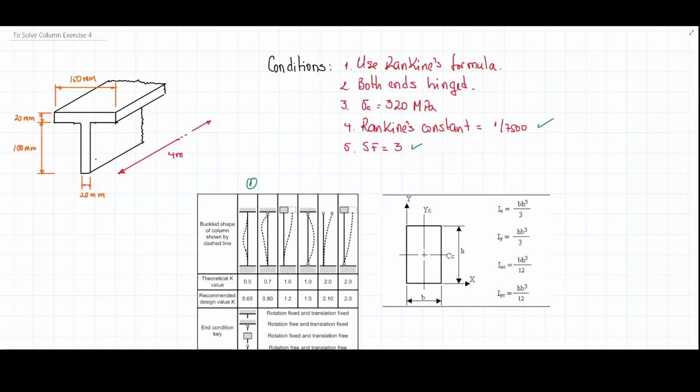I have a couple of tables here. The first one notes, for example, the ending termination of each one of the columns, because let's remember that the physical length of a column is totally different from the effective length taken into consideration in the buckling formulas such as Euler's, Rankine's, or Johnson's formulas. We need to take care of that because, depending on the type of ending of the columns, the possibility of deformation is going to be different in each one of them.